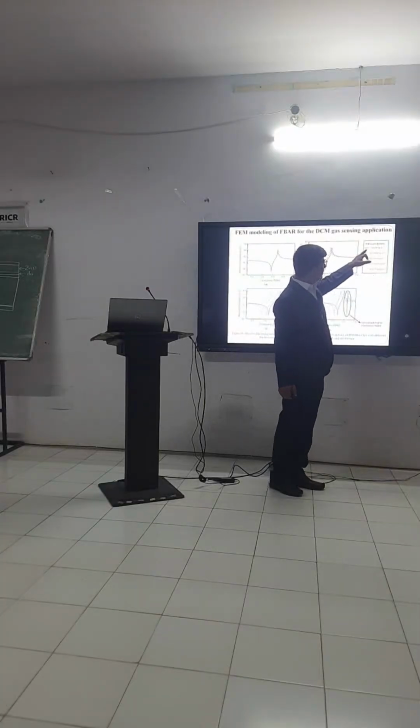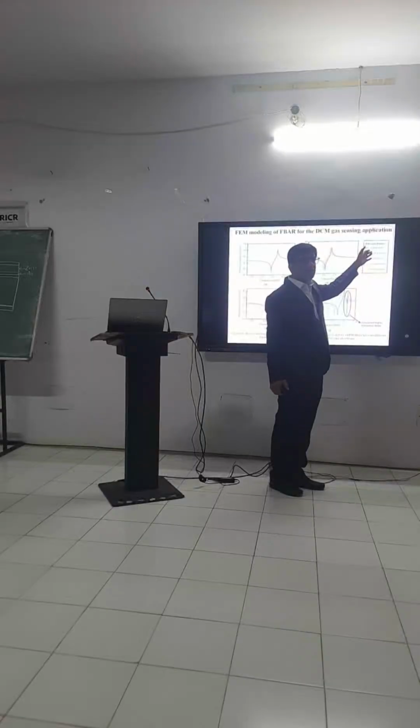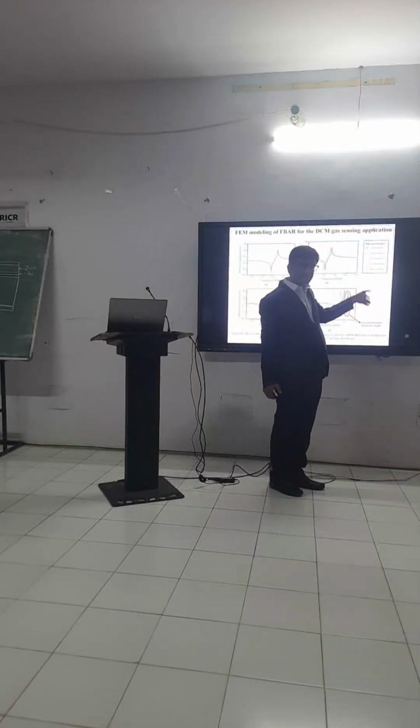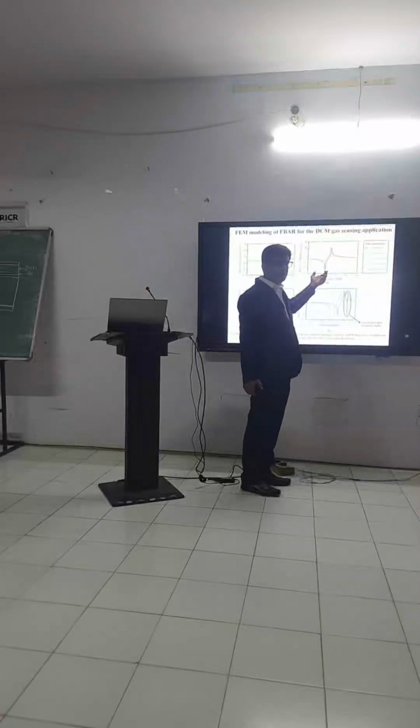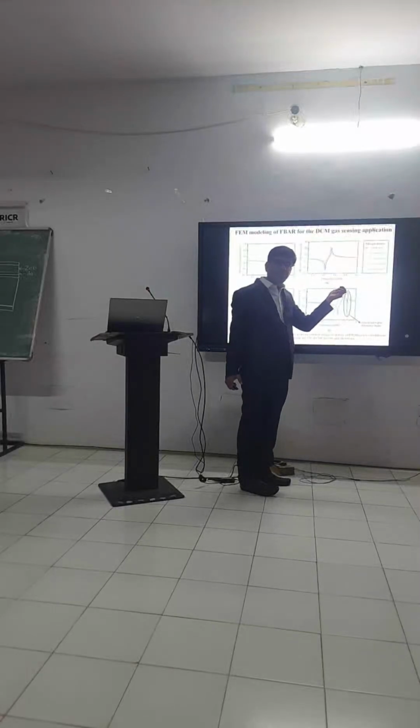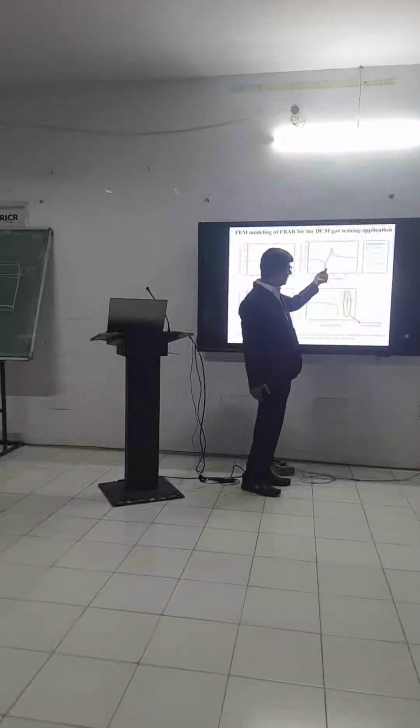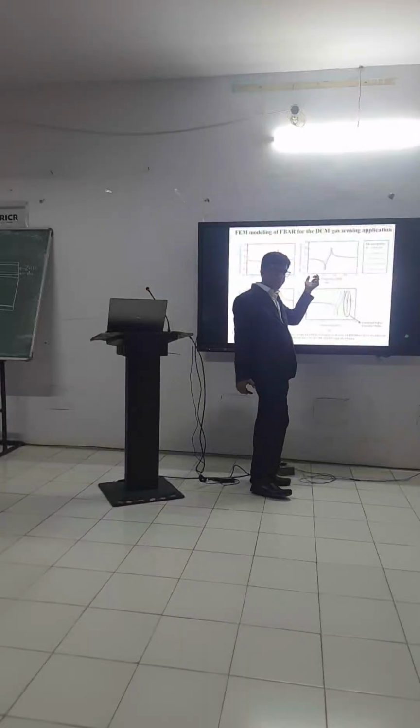What I am doing here basically is increasing the concentration of gas. What do you mean by concentration? If I increase the concentration, basically what am I increasing? I am increasing the density of the sensing layer. So if you increase the density of the sensing layer, what will be the response of your filter, resonator? Its frequency will change based on the concentration of gas. So see here, a little bit of change in the frequency.